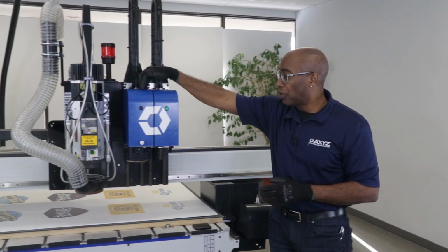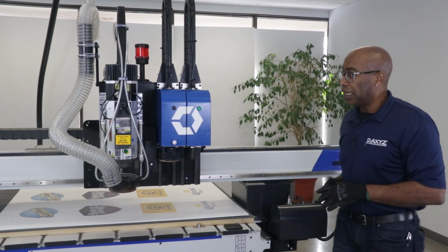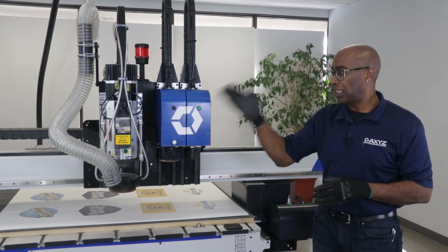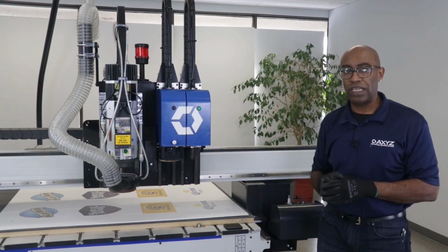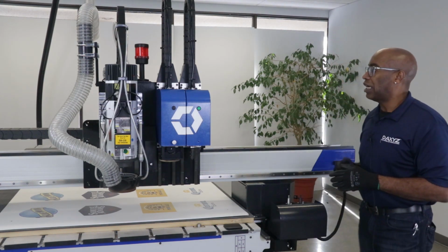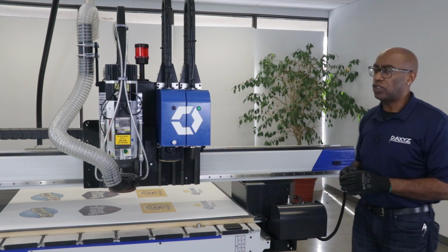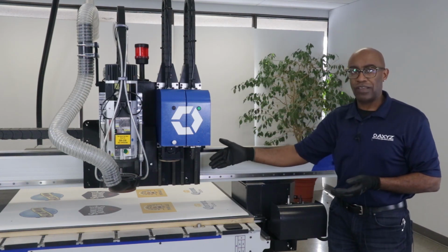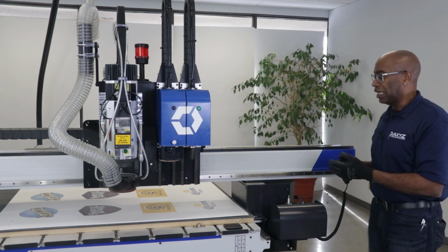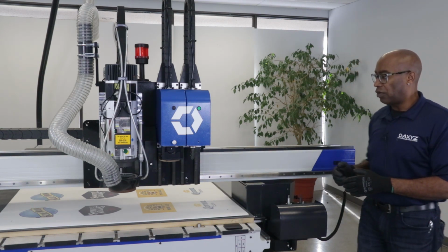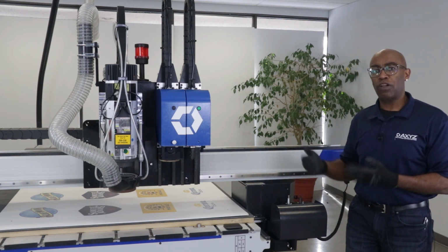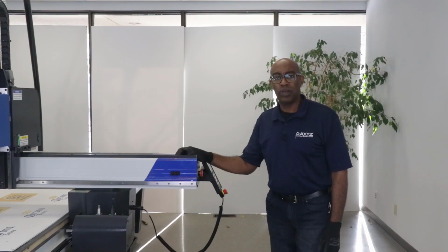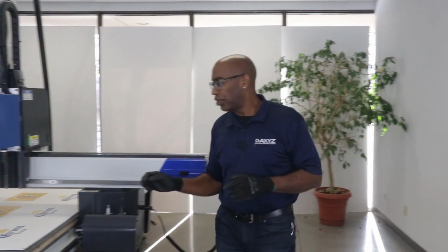Next to that is my electric oscillating knife. And then we move on to our spindle and ATC. So similar to the Infinite, I have a 10 horsepower spindle and a 10-position ATC. Another unique aspect of this machine is that it traverses at 2,200 inches a minute, and I have a lot faster Z process. So for this particular application, we have a higher feed rate and a higher plunge rate to basically get you higher throughput. Okay. So now we're going to run the AVS job on the Trident.